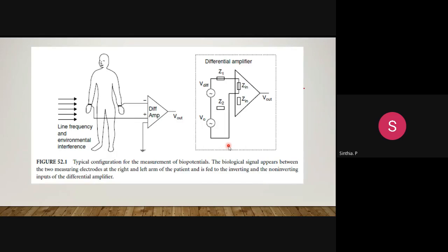If you see this figure, the electrodes provide the transition between the ionic flow of currents in the biological tissue and the amplifier. They represent a complex electrochemical system, and they determine to a large extent the composition of the measured signal, right? So the preamplifier plays the most critical part of the amplifier itself. Why? Because it sets the stage for the quality of the biosignal.